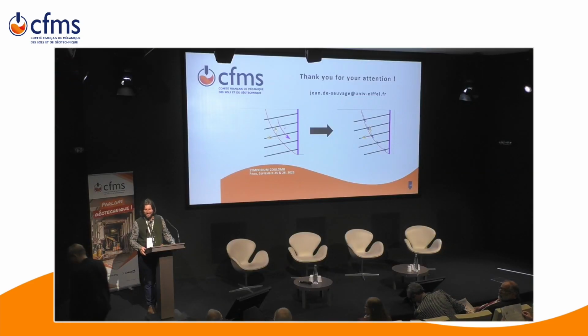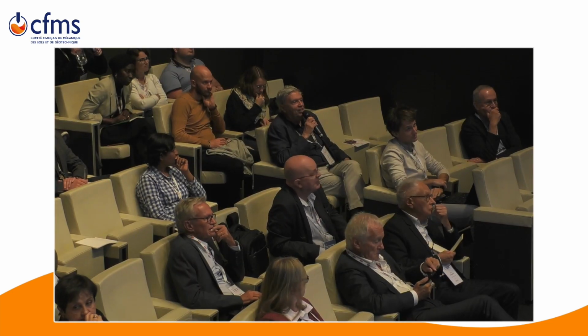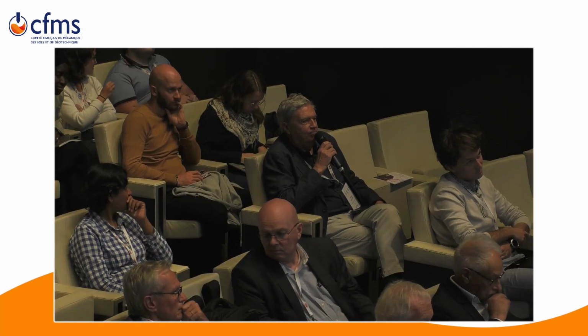Okay, Patrick. Did you have access in the centrifuge tests to the shear force, so the measurement of shear force in the nails? No, it was only okay. The nail was 2 millimeters in diameter, so we were only able to put an optic fiber at the center, as a neutral fiber of the nail. It's a bit too small to be able to measure anything other than the tensile forces.